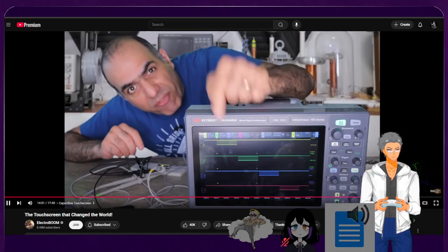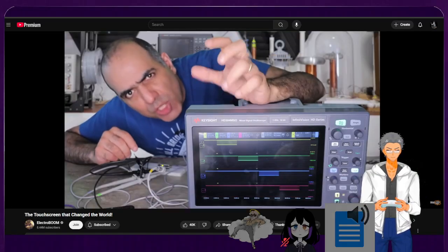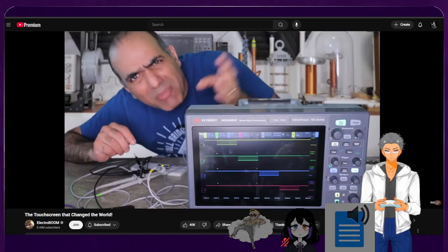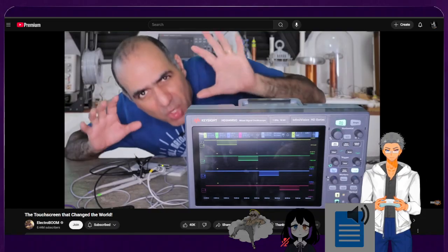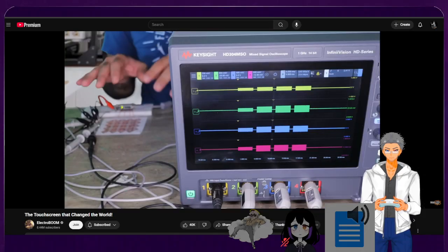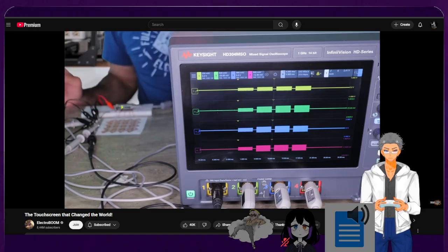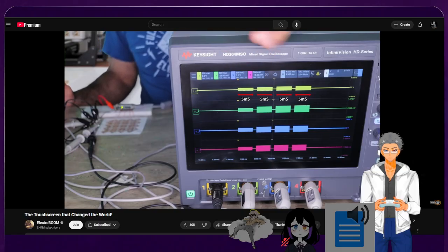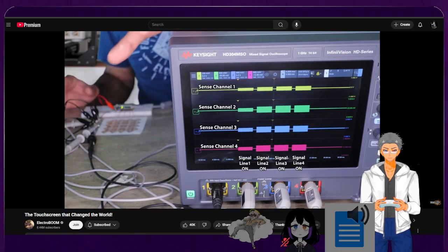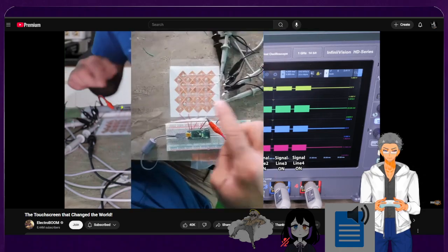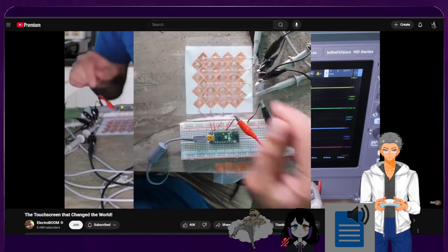Board to create these 4 bursts of 62 kilohertz square wave, 19 millisecond wide each with 1 millisecond gap between them. And I'm gonna feed this into my signal lines. And now I look at the 4 outputs on my scope aligned with the input signals. I change the on time to 5 milliseconds for faster refreshment. You see the effect of each input turning on all outputs because they all run side by side.